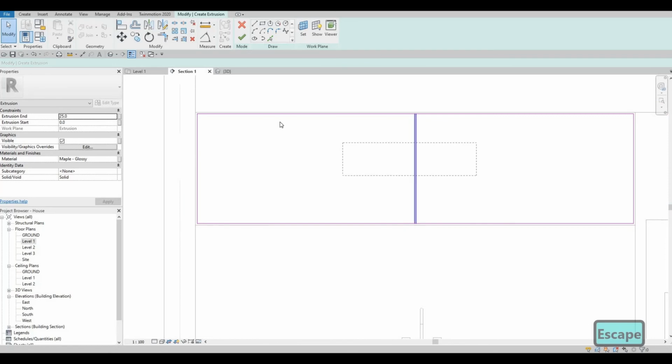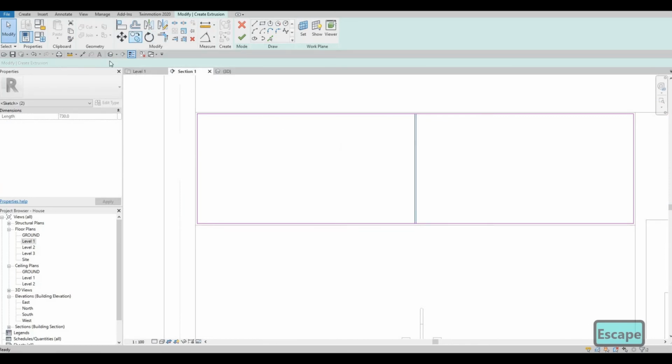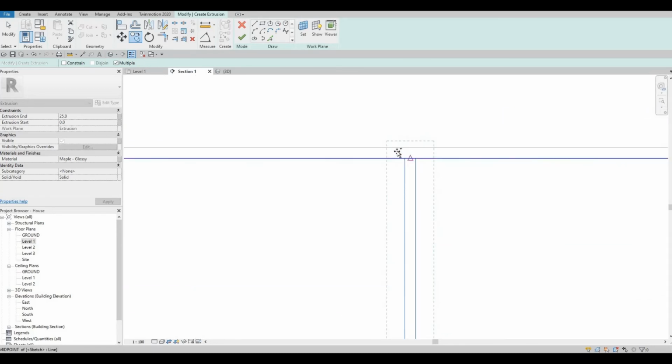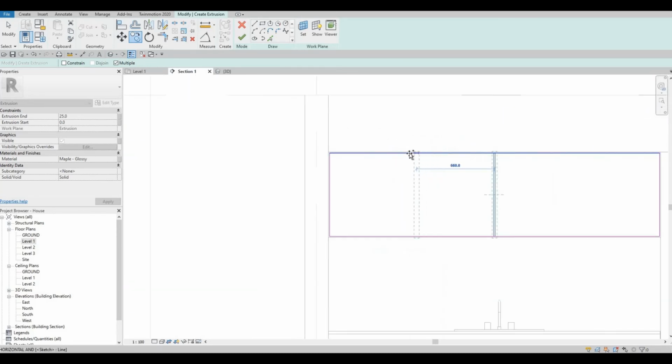And then after this, from here I'm just going to copy this. So copy command CO, and then here we're just going to copy it in the middle of this. We could probably add, so here we have this width, so around 1400, and then the 1400 we can divide it by 3. So 1400 divided by 3, it's around 460.